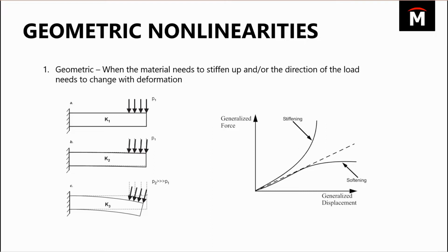But as soon as you put more on it, we know that diving board gets much stiffer and it gives you more spring back. And it needs to stiffen up to give you the proper answer. That is a nonlinear response in itself. But the other thing that's happening at the same time is the direction of the loading needs to change. Initially, the force arrows, or your weight on a diving board, are going straight down. But as soon as that starts to bend a relatively large amount, those arrows aren't going straight down anymore. So updating that type of force input is also a nonlinearity.